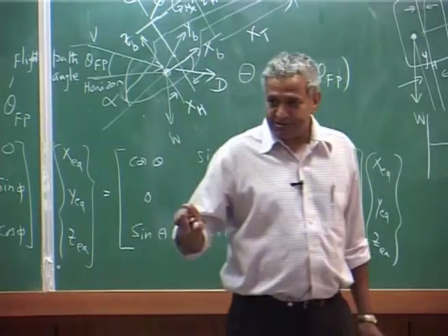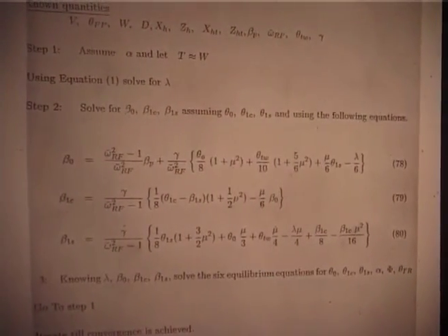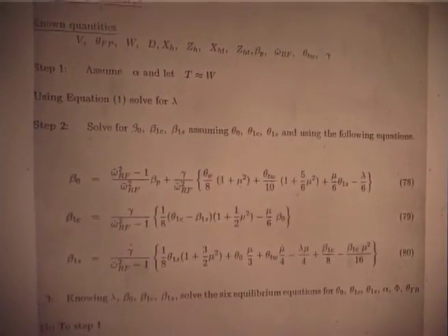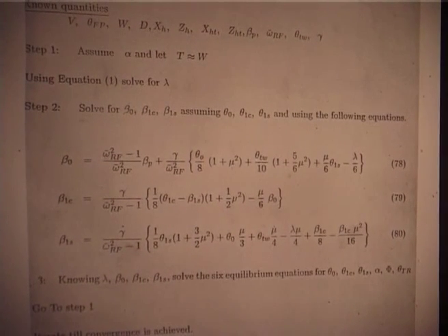And once you converge in the pitch angles, then you say your result is over, but you will never get everything equal to 0 beautifully. Some small number, that is okay. If it is 4000 kg, if it comes to 3950, all right, 980, because otherwise it will keep on oscillating, the result will keep on shunting. And these iterations, if you go real complicated thing, the problem which we solved, it takes 14 hours for one flight condition.